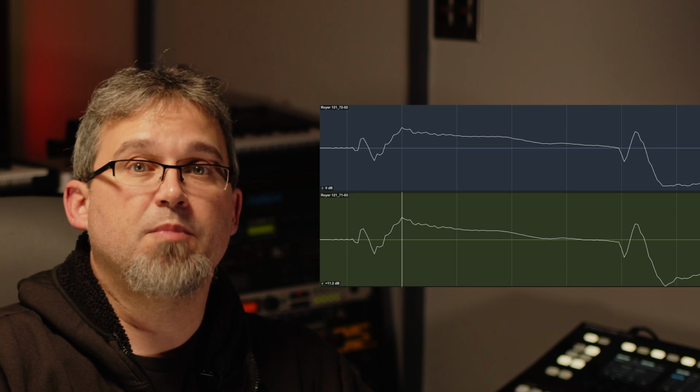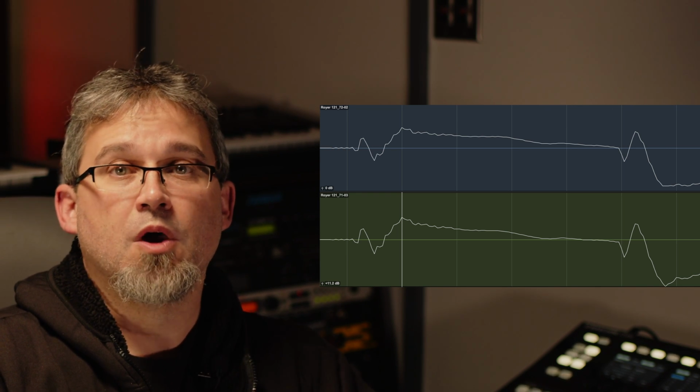We're looking at a 12 dB gain difference in some of our tests here, so while the amplitude is lower, the transient certainly is not different enough to make a claim that the higher impedance makes transient sharper. Louder? Yes. Sharper? Absolutely not.